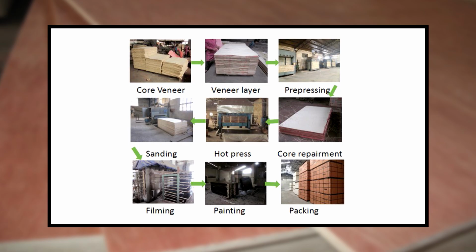As the lathe rotates the blocks rapidly about its long axis, a full-length knife blade peels a continuous sheet of veneer from the surface of the spinning block at a rate of 300 to 800 feet per minute. The long sheet of veneer emerging from the peeler lathe may be processed immediately, or it may be stored in long multiple level trays or wound on rolls.